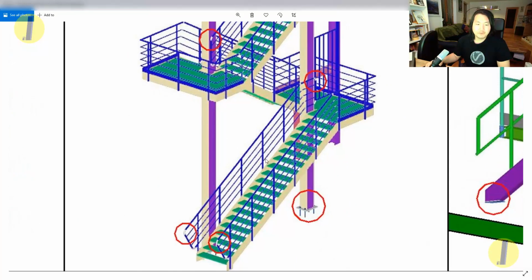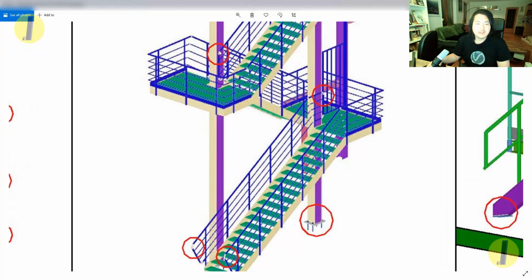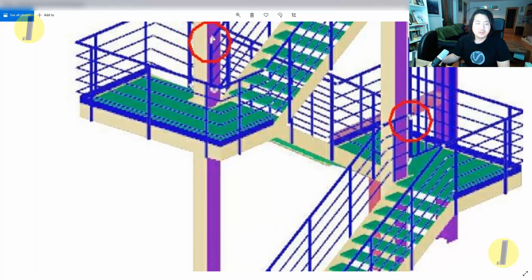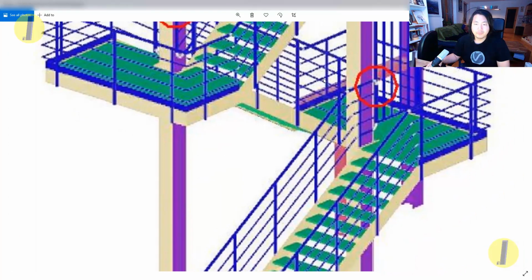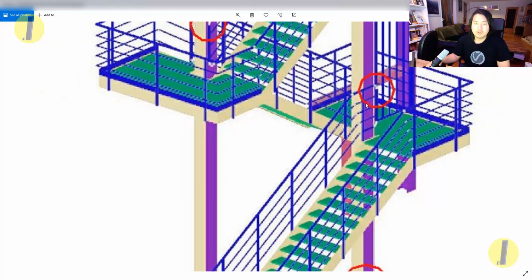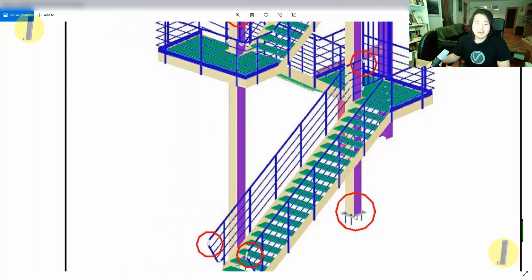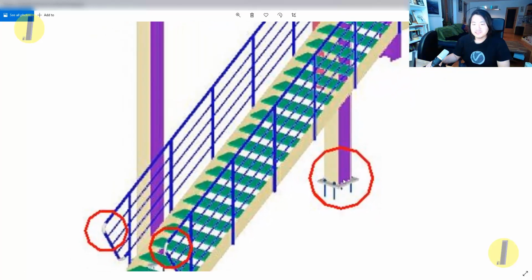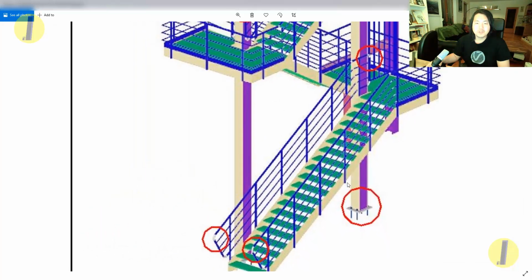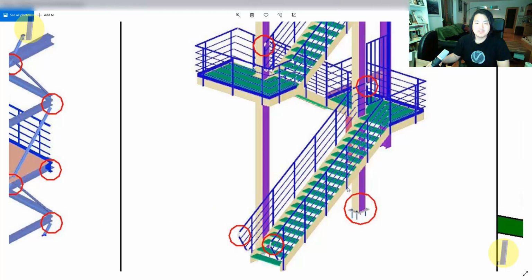Whereas if you set the higher level of detail in terms of steel connections, between steel handrail, or the joint between columns and the beam, or column plate with all these bolts and nuts, in that case, if you don't specify or classify these steel connections, these collisions may be reported as millions of collisions in your Solibri model or Navisworks model.